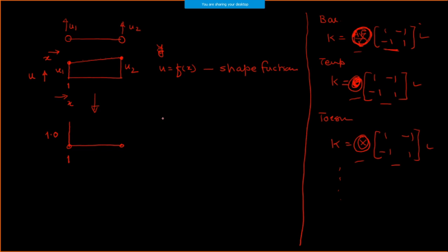We are going to use it for this. So this is what normalized means for a particular node. If I'm going to define a shape function for this, it is a unit deformation I'm going to look at. That may be a displacement in the x direction, y direction, or z direction, anything. Another one may represent temperature. That one may represent torsion, that is theta is also a parameter. So this is what a normalized displacement is.